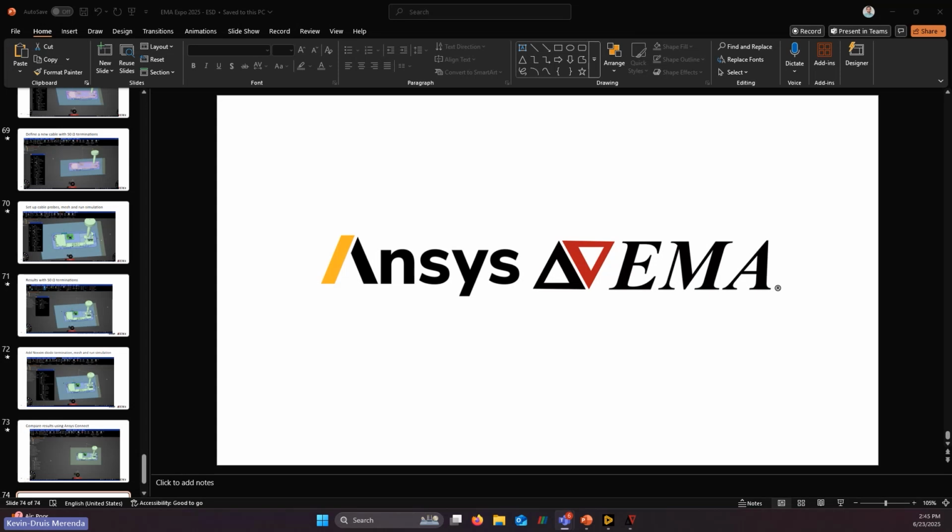There's also a lot of additional tools within the variable mesh tool. There's a way to make sure that the mesh aligns with specific parts of the geometry so that the grid is exactly the size of your geometry. This is useful for antenna simulation as well, making sure that the grid is lined up well, and you represent with the highest fidelity possible the size of your geometry in your antenna.